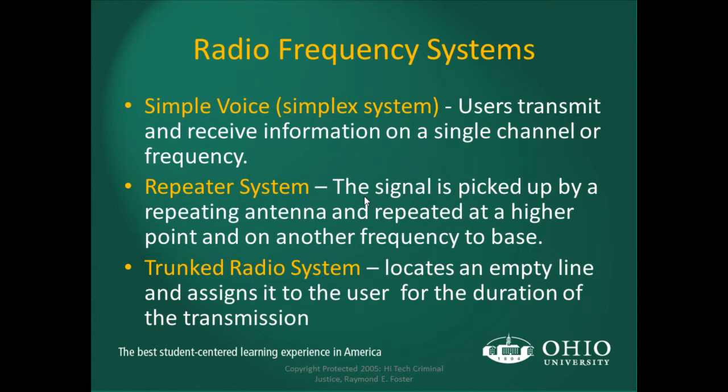We're talking about radio frequency systems. Simple voice here means users can transmit and receive information on a single channel. I'm talking on it, and everybody else has to listen. When I let go, then I can listen. So it's a simple, or simplex, system.